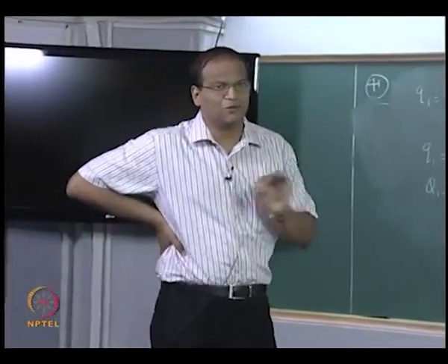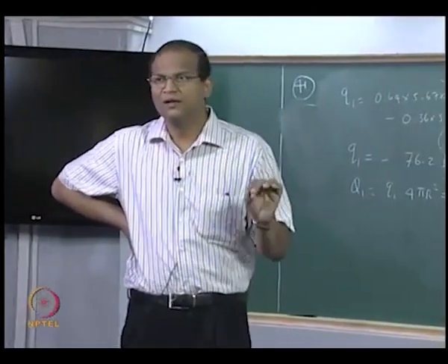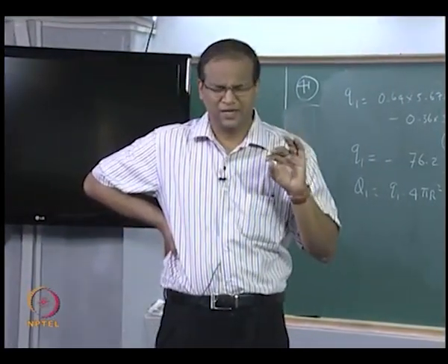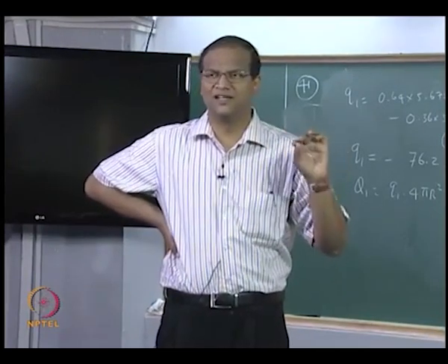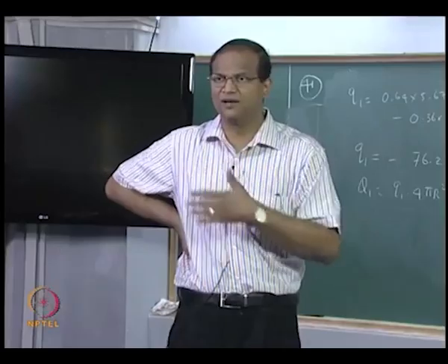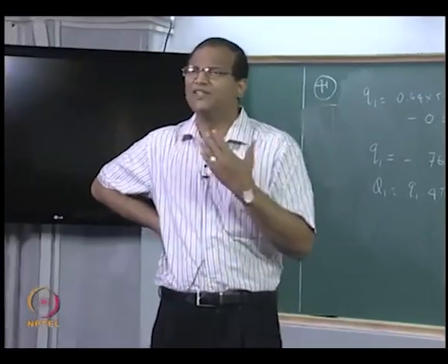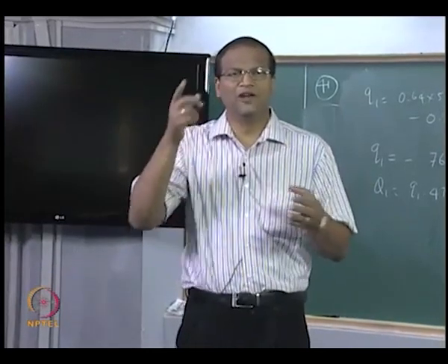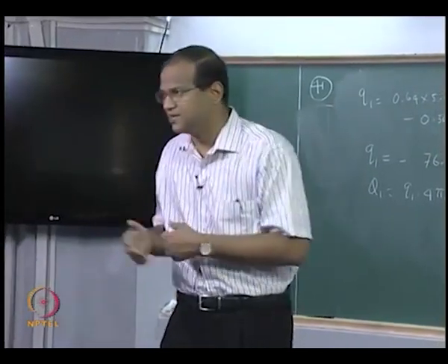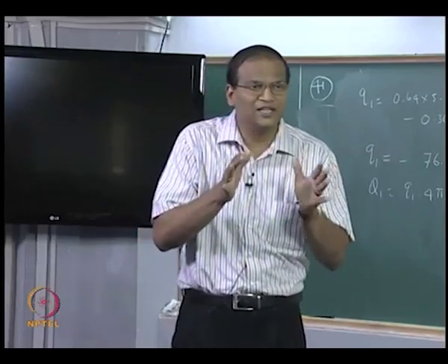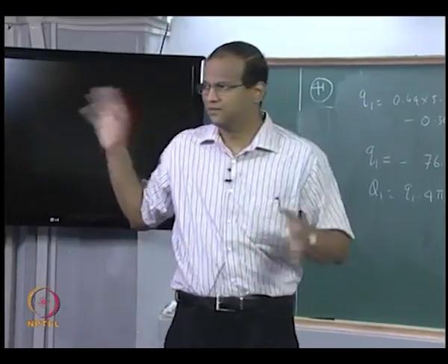So the last few classes basically come under the category of engineering treatment of gas radiation, because this is an engineering treatment. It is a recipe, a very quick way of solving problems by using charts and getting the properties. The complete detailed way would be to solve the equation of transfer for various spectra. There is no need to define an overall absorptivity and transmissivity in that case. Then you will work out the intensity or the flux in each of these intervals and integrate.